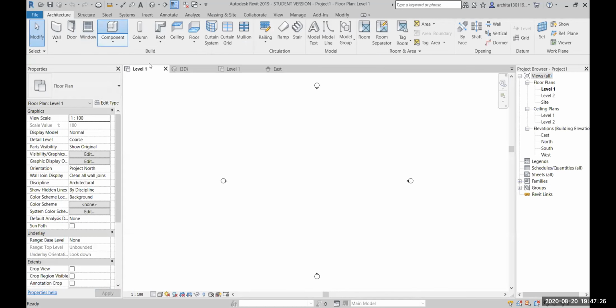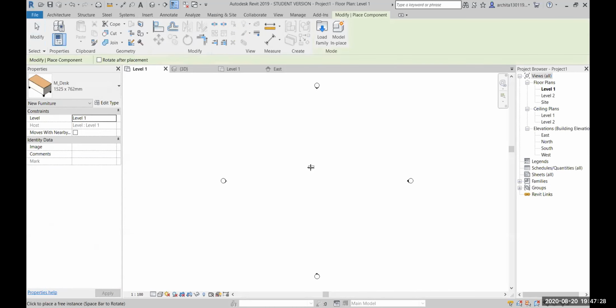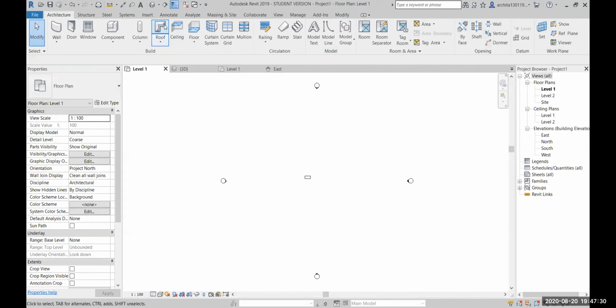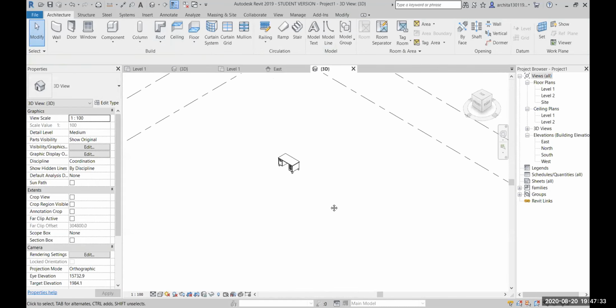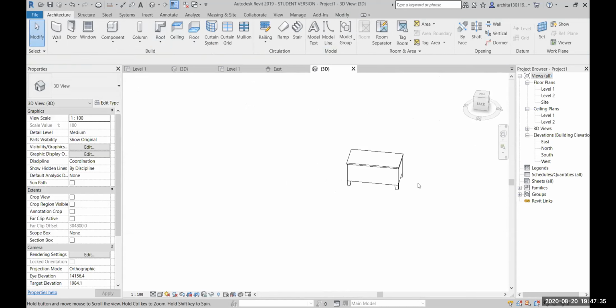Ma'am, can you tell me one thing again? Yesterday we were not able to select the top surface of the cuboid, right? You have to select the vertical plane first. Okay. Make the vertical plane your work plane, and then you can select the top and bottom surface.